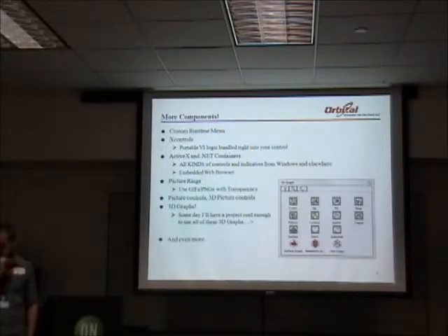A couple ones to mention, an embedded web browser is right on the palette now, and it's just a .NET container. And you send it the web page you want to load, your test results or whatever, and it shows up on your front panel. So you get all of that Internet Explorer or whatever browser functionality in the LabVIEW container. It's nice.